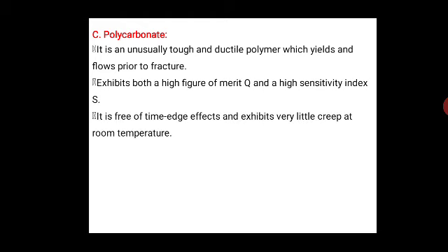Polycarbonate is a thermoplastic and is produced in sheet form by an extrusion process. The material is available in large sheets with reasonably good surface characteristics. But the extrusion process usually produces some residual birefringence in the sheets. Annealing for an extended period of time near the softening temperature is required to eliminate the residual birefringence.